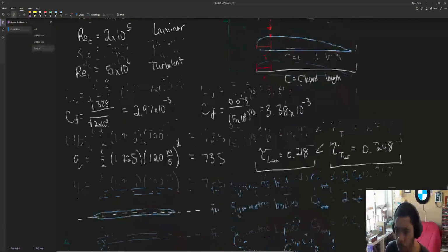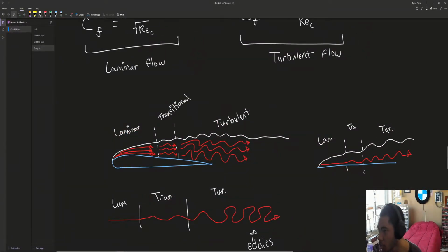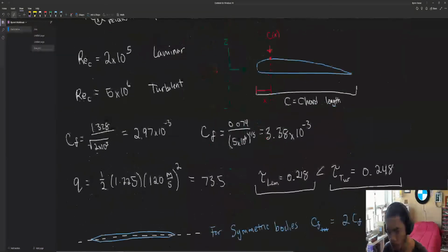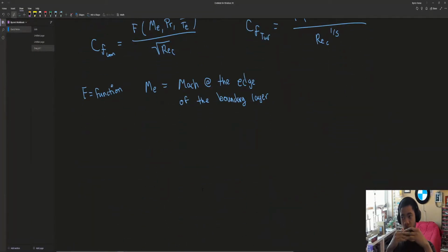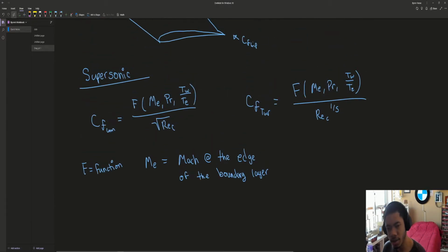So if we go back up and take a look at our boundary layer, the edge of our boundary layer would be here. This is important because, as we talked about before when we talked about lift, the velocity inside the boundary layer goes from 0 up to essentially what is the current free stream. So it is important to know how thick the boundary layer is, and that can be found out. We use the symbol small delta, and this refers to the boundary layer thickness.